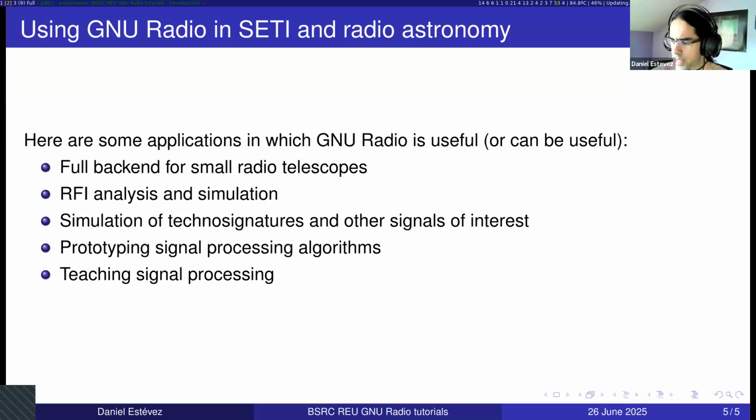Okay, so let's get to more fun stuff. I have in here an RTL-SDR radio, and I think you might have one of those. So probably Steve has handed you one of these radios. They might not look exactly the same, but they have a USB port, and a port here that might be a different connector type where you can connect an antenna. And this is the radio we will be using to sample radio frequency signals on our computer and to do some experimentation in these sessions.